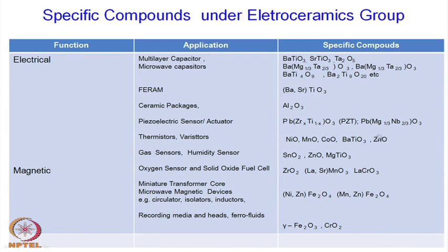These are some of the materials which possess this piezoelectric property, and they can be used for sensors and actuators. The reverse is also true. As I have just mentioned, piezoelectricity means you generate voltage against mechanical stress. The converse is also true. You apply an electric field and you generate mechanical strain. So, the dimension gets changed as you apply the electric field.